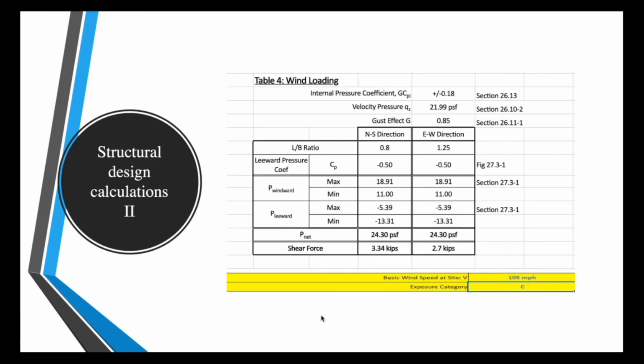For the wind load calculations, we used Microsoft Excel to find the Kzt, the C and G values from the IBC building code. For each wind direction considered, an exposure category that adequately reflects the characteristics of ground surface irregularities shall be determined for the site at which the building or structure is to be constructed.